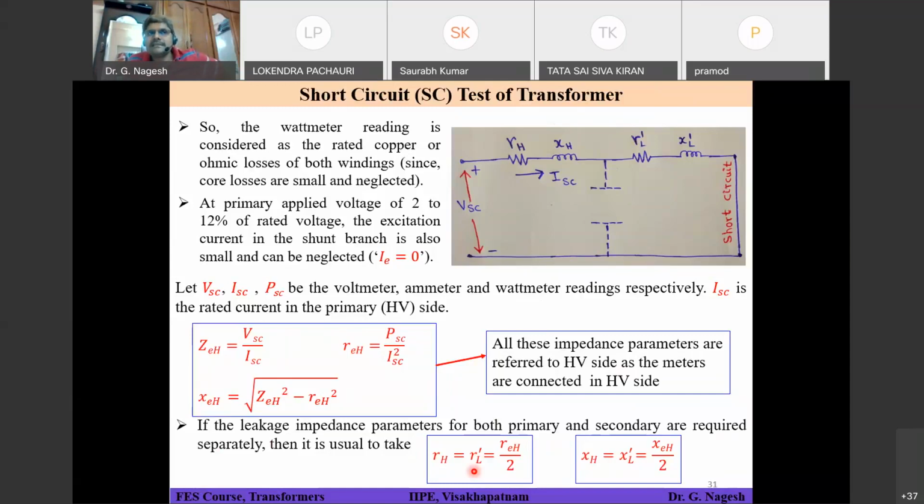what you have indirectly stated is also correct. It depends upon the turns ratio also. Okay. This RL dash you are calculating, that means REH you are calculating from the voltage and current on the primary side, on the HV side. So I have already stated RL dash is the equivalent resistance which is seen from the source. You understood? Yes, sir. RL dash is the equivalent resistance which is seen from the source in the primary winding. But actually this RL dash is related to the secondary winding. But equivalently it is what is seen from the source.